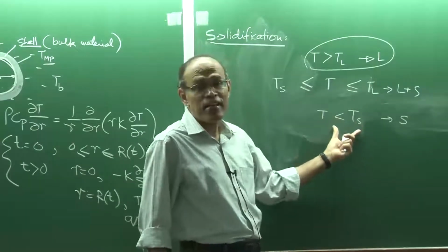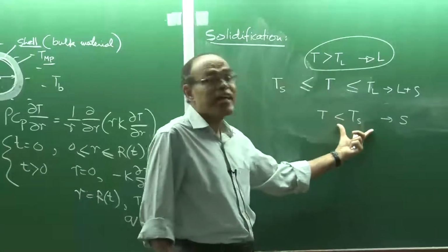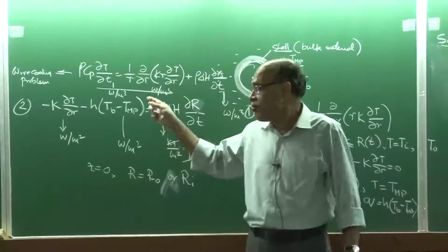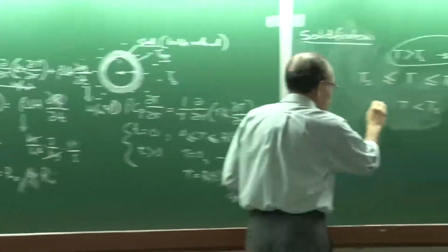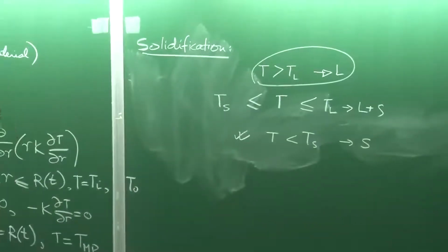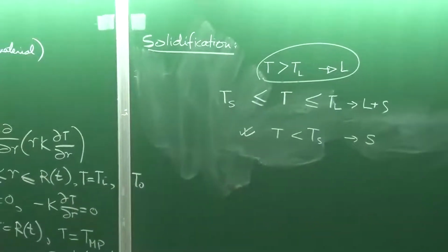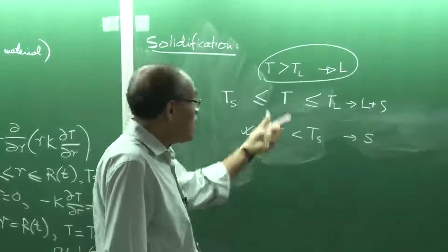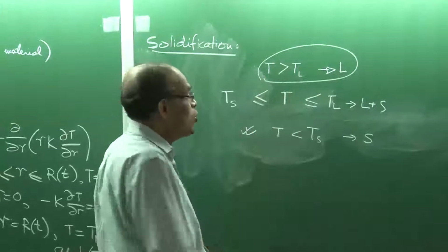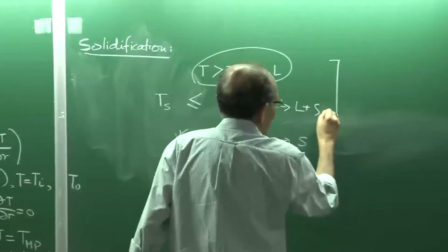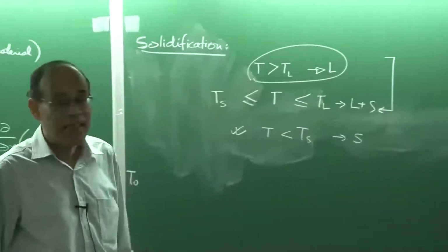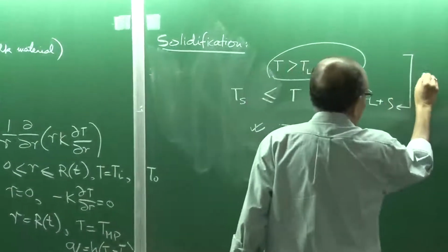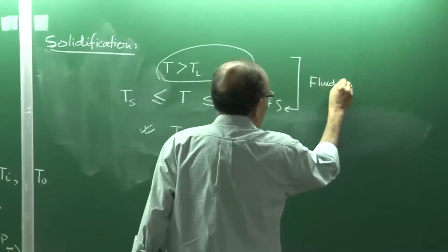And in the final stage, this phase is akin to the problem that we have discussed for furnace cooling or wire cooling. This part is already explained: how we can formulate the cooling of a solid and how we can address the temperature field. But the liquid phase requires knowledge of the flow to tackle. So not only is heat transfer important here, but the fluid flow controls the heat transfer phenomena. So it's a conjugate problem of fluid flow and heat transfer.